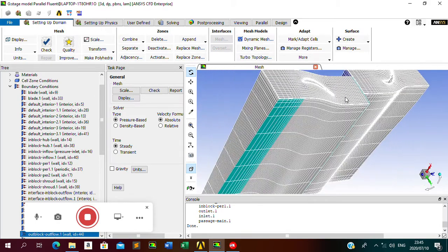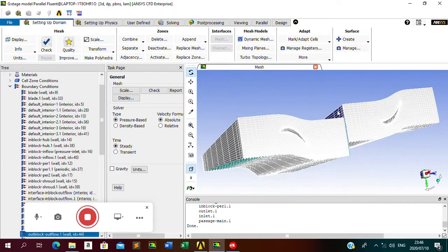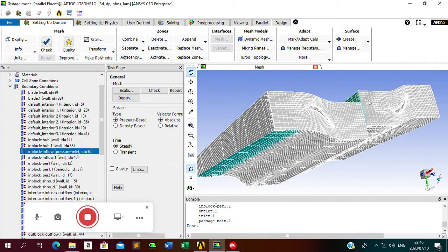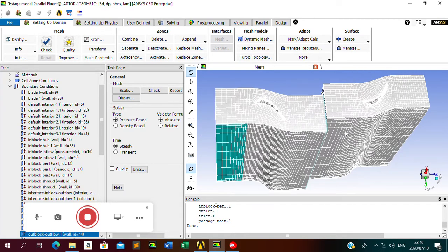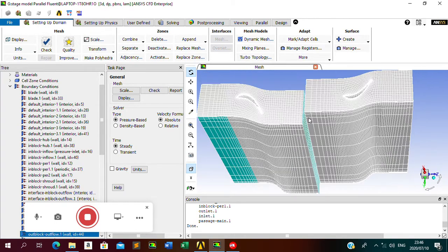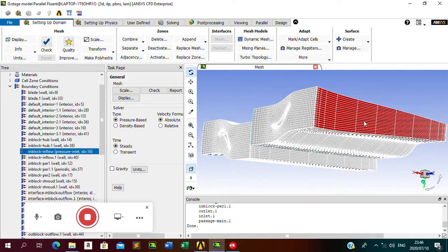So typically what we would have here in this simulation is my flow will go from here. So I'll have my fluid flowing through this, coming through this boundary here, into this boundary, this one here. So these two boundaries that are called interface zones, I'm going to link them together so that whatever comes out from here actually goes to here, right? And then it will exit here.